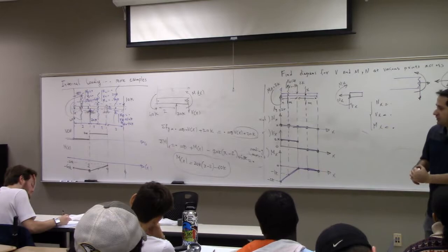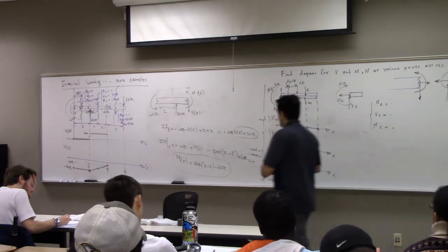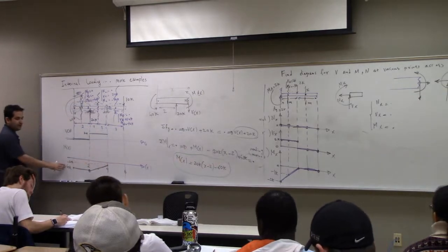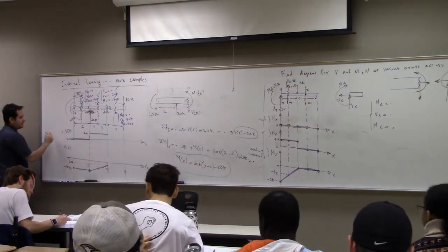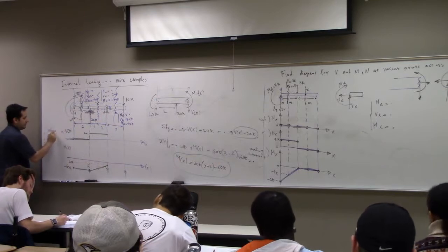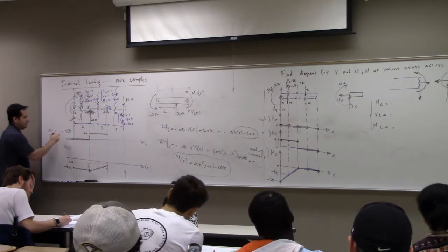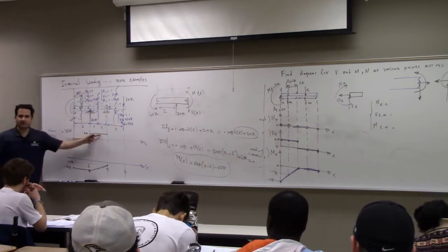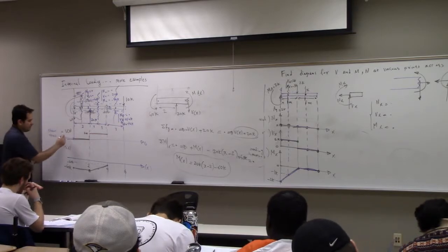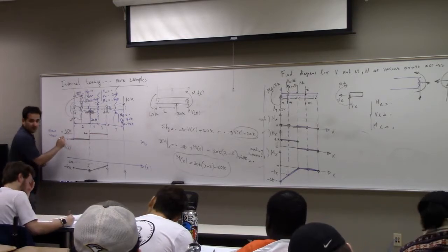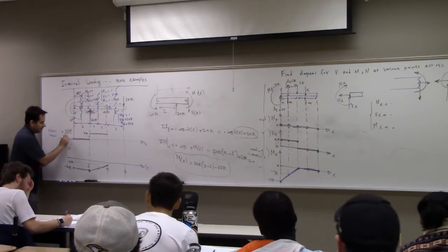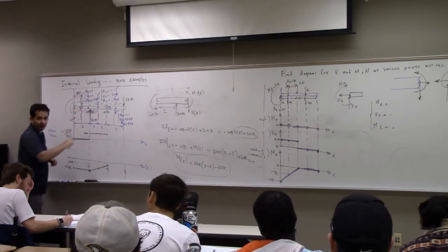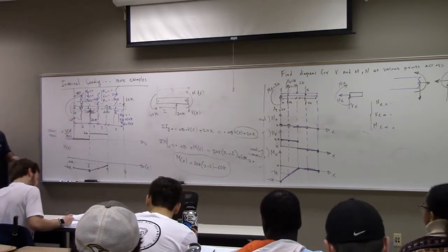So there is another diagram called a stress. So bending moment gives you some sort of a stress that we'll study later. This guy gives you shear stress diagram. So in order to get shear stress diagram, what do you do for average shear stress diagram? It's going to be exactly the same diagram, but it's just scaled. Why? Because you divide this by the cross-sectional area at point X. Right? Because the cross-section area can change too. Right? It's not the same.